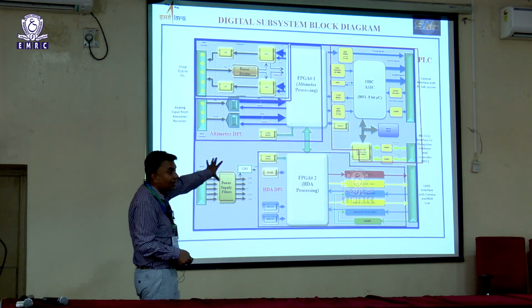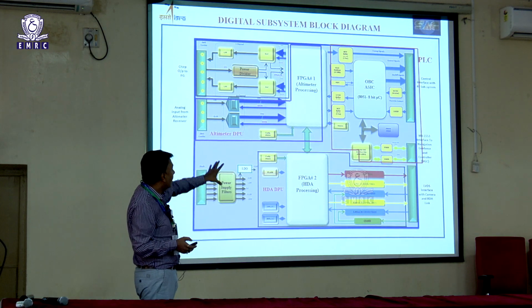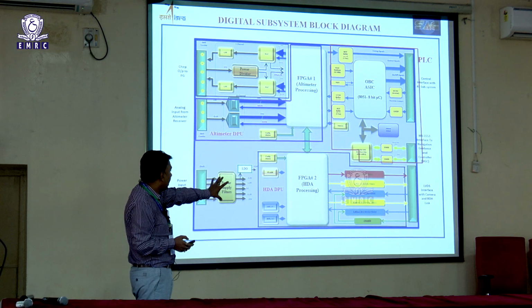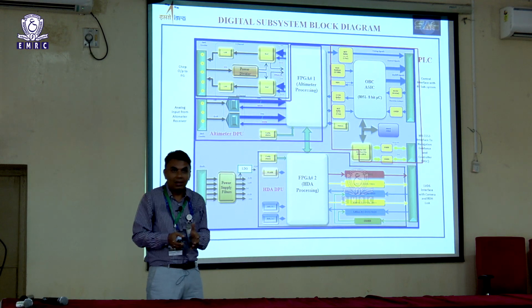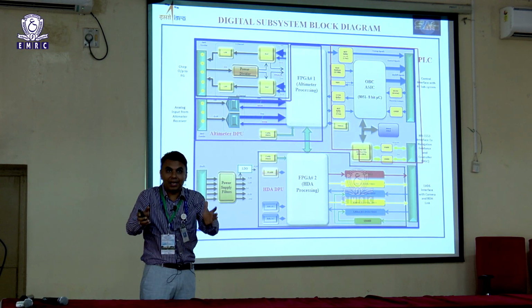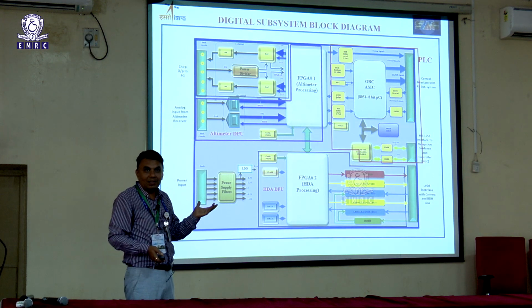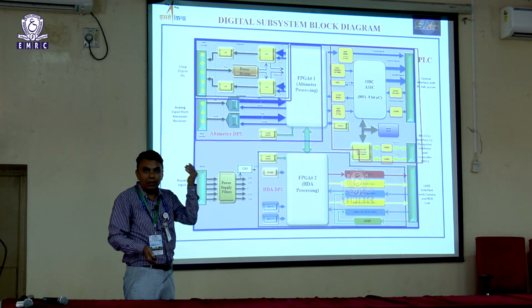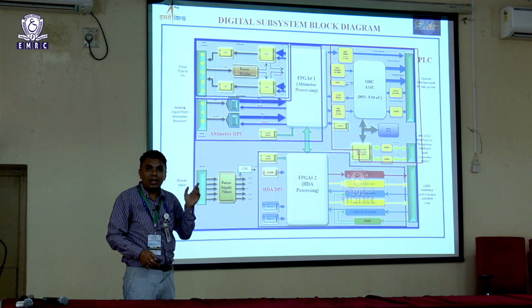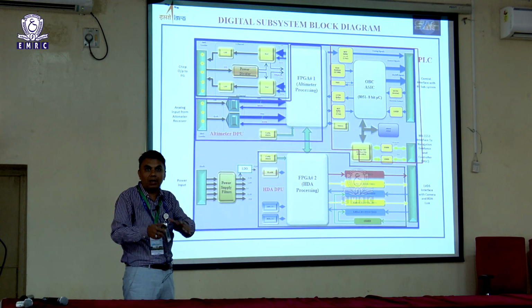Now this is the internal design of Chandrayaan 3, where we divided it into a 3-part design: 2 FPGAs plus 1 ASIC. The altimeter part is in one FPGA, another part does the image processing, and the third part is where the control segment sits together. All this we have designed in a single board, and we have added reliability: the same card has a replica, main and redundant. That's why we are confident this time that even if everything fails on one, the second card will pull on, and there should not be any immediate failure. In Chandrayaan 2 we had one such card, and there was a software bug in it, which is why we didn't take a decision at the right time. Here, two such cards are sitting there, working independently.